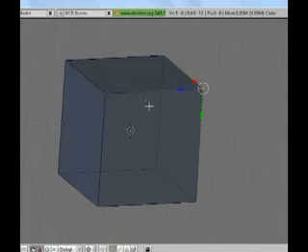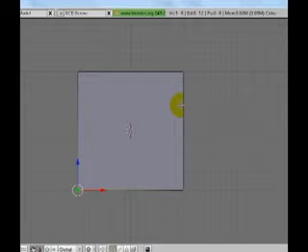Okay. So now you notice that when I right click, this is how you select everything in Blender, you use right click. So when I right click on the vertex, these helper arrows come up. Now if you want to move a vertex, you'll stretch the cube in the direction that you move the vertex. In 3D mode you're going to be a little bit inaccurate moving things. You can switch the views by pushing 1 or 3 or 7 like before.